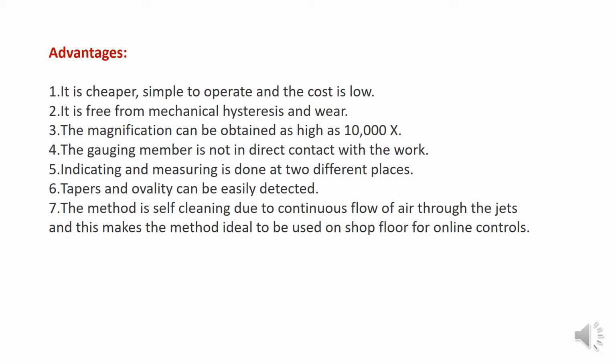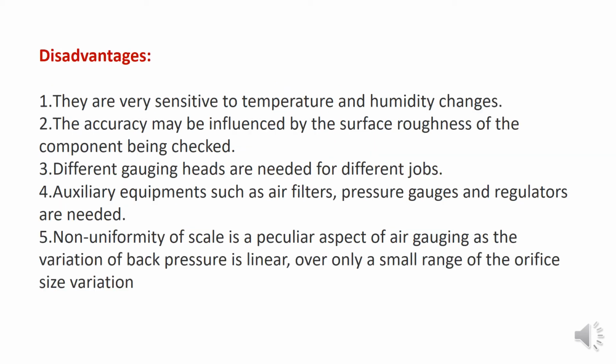Taper and obliquity can be easily detected. The method is self-cleaning due to the continuous flow of air through the jet, and this makes the method ideal to be used on the shop floor for online control.